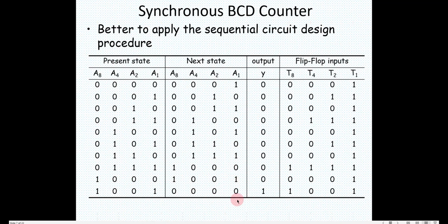So how to realize the circuit? One option is, I make 4 flip-flops like we learnt about sequential design. How to do it? We write the present state, we write the next state, and then if you have to implement it with D flip-flop, we write what is D, and then try to use a K map to find out what is D, or if we use JK, that we saw in the last class, how to design a sequential circuit.